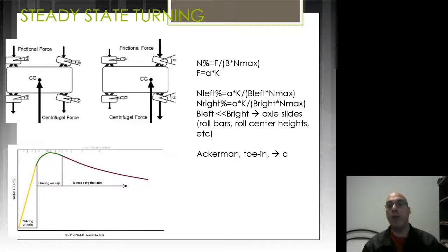So this is one thing you might want to look into when setting up your vehicle when you change the springs. Aftermarket springs, you usually have stiffer springs in the back, and it will change the attitude of a front-wheel drive car towards more of an oversteer setup. And that will make you significantly faster.